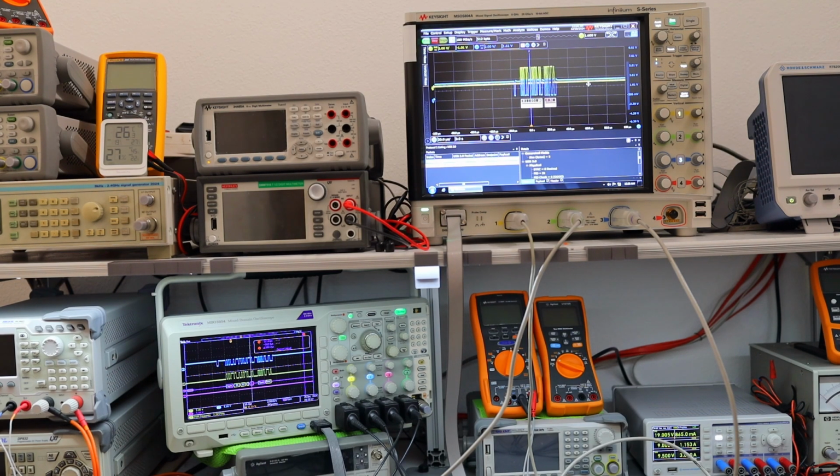We'll see how easy or hard it is to probe USB 3.0 with an 8 gigahertz oscilloscope and very, very limited bandwidth 2.5 gigahertz probes. We have one 4 gigahertz probe available to us, and a few 2.5 gigahertz probes are also available. Most likely we will be able to get away with decoding USB 3.0 with a 1.5 gigahertz probe. We'll try to find out if we can make sense out of the data.